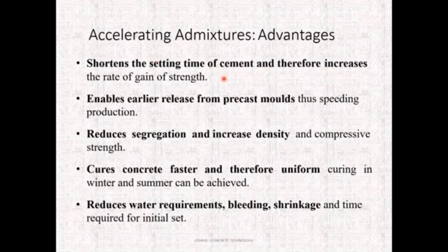The advantages of using an accelerator: it shortens the setting time, and therefore increases the rate of gain of strength in concrete. It enables the earlier release of precast molds, thus speeding up the production process. It also reduces segregation and increases the density and compressive strength of the concrete. It cures the concrete faster, and therefore uniform curing in winter and summer can be achieved. It reduces water requirement, bleeding, shrinkage and the time required for the initial set.